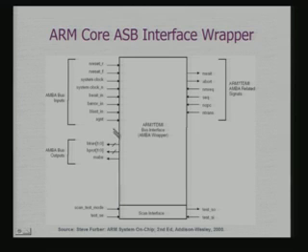Also, the size information that we provide in the AHB bus would be obtained from the outputs provided by the ARM chip. So, this is basically an interface unit. With the CPU core, typically you design an interface unit to provide it with the ability to communicate on the AMBA bus.